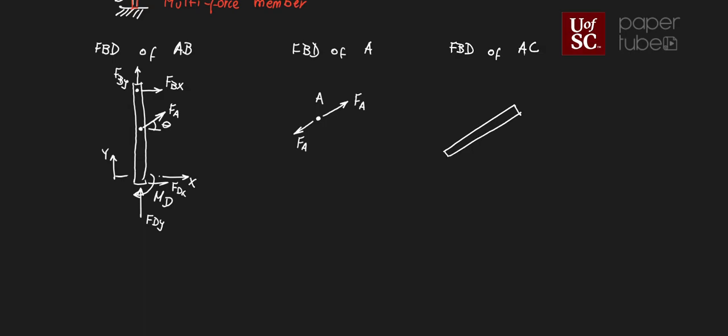All right, we're going to have a force that was coming from that place, from A, and there is a force. It has to be in the other direction, right? So this is FA, this is going to be FC, right? The only way that two-force member is in equilibrium is that FA is equal to FC.